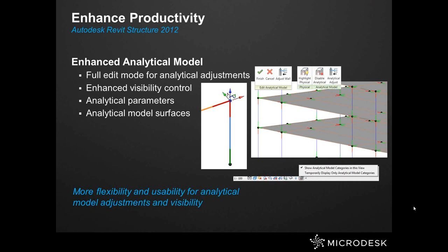There is also an Adjust Wall feature. Analytical walls can be adjusted so that their end edges correspond with other analytical wall edge or wall surfaces. These changes improve Revit Structure's ability to manipulate the analytical model to help solve round-tripping issues between Revit Structure and structural analysis software.